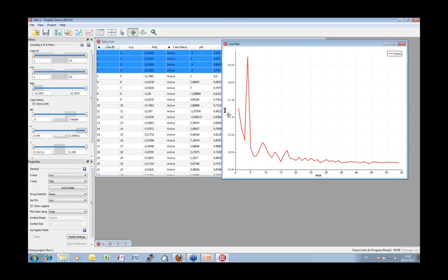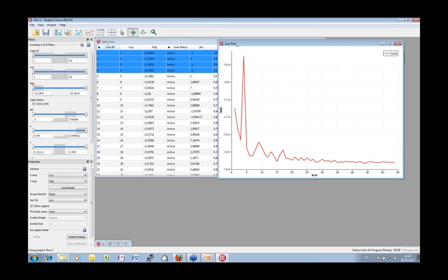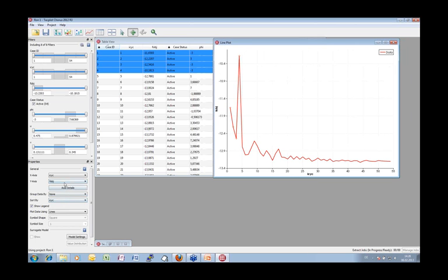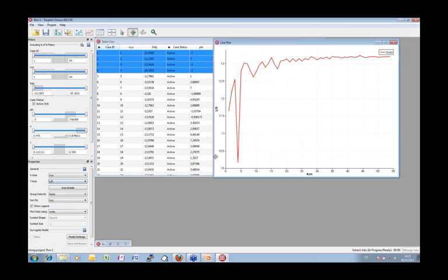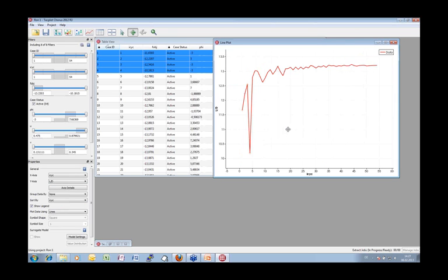But can you switch the design here of objective? Thank you very much. Of course, this is wrong, so I have to switch to L over D, right? Because the optimizer always searches for a minimum, so I have to switch the sign of L over D, and we searched for a maximum.